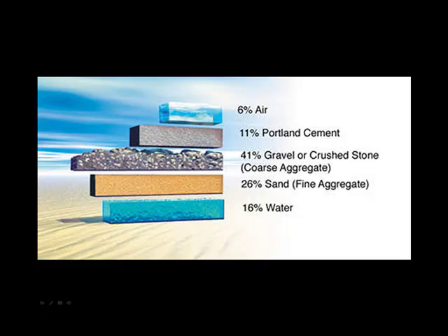Could be some kind of gravel or broken stone. That produces a very good result. And if you want to have a little clue in the back of your head of the proportions, 1 to 2 to 3.5 I think would serve you well.